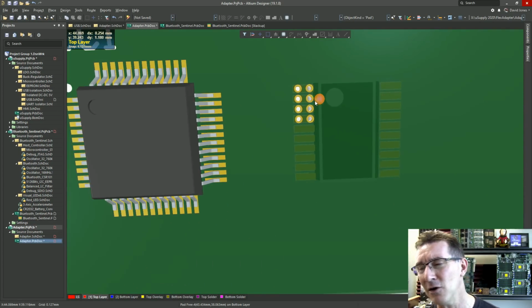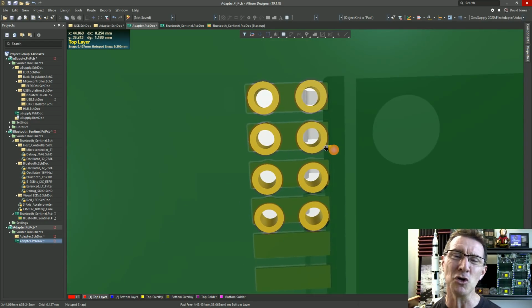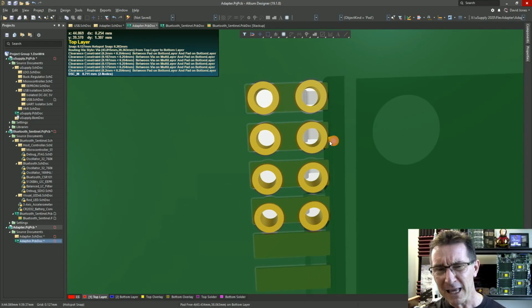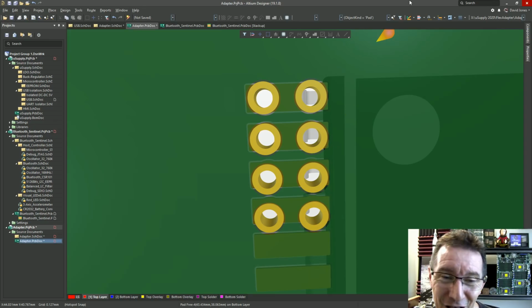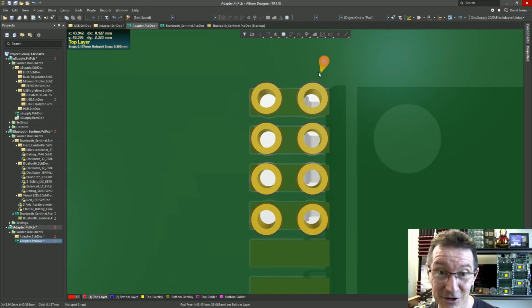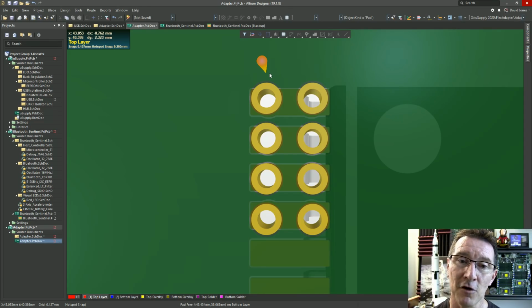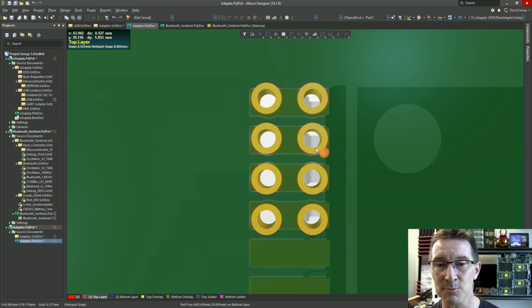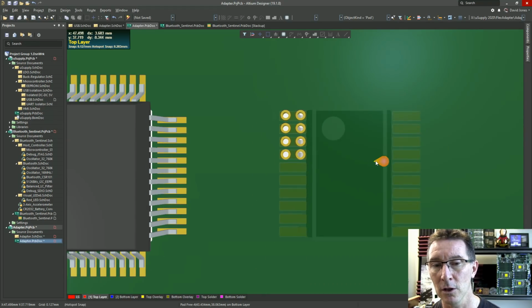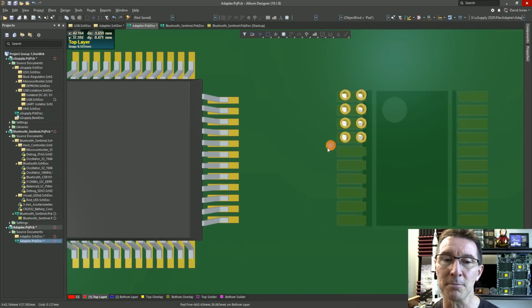So I don't know. Should I go? People are screaming, use 1, Dave, use 2, go for the castellation ones. Now, of course, if I wanted to do the castellated holes, I would just specify my board outline as going right through the center of those pads, and then they would manufacture it. They'd cut it, get the laser out, straight through, and then I'd be left with the castellated pads. But anyway, I think 2 like that will probably do the business.